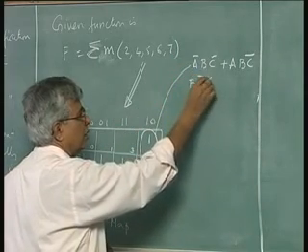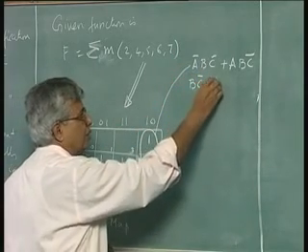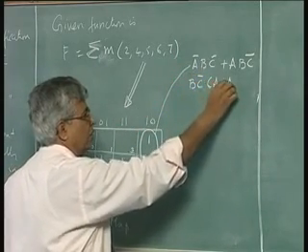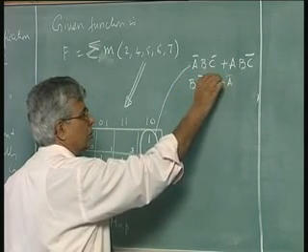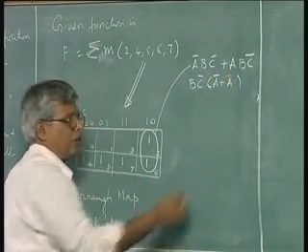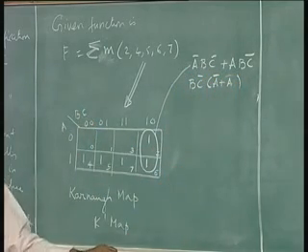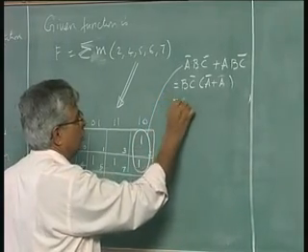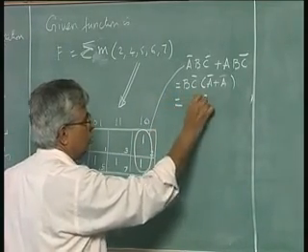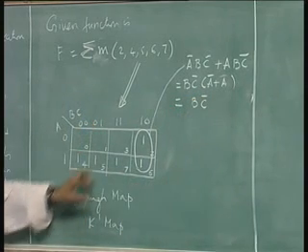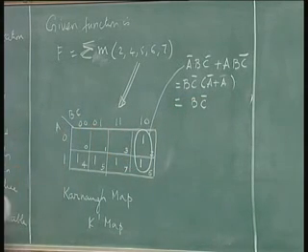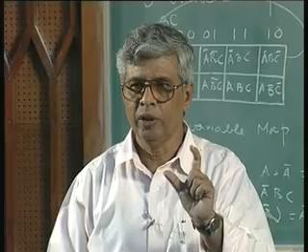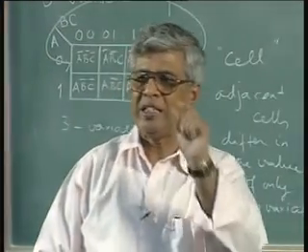using that distributive property, A plus A bar is 1. And since A plus A bar is 1, a known identity, these two cells can be merged or combined into a single term of BC bar.